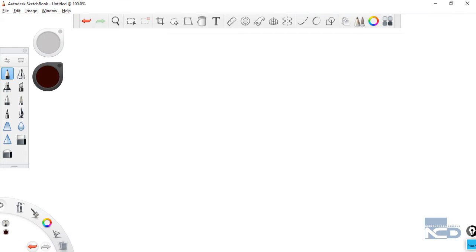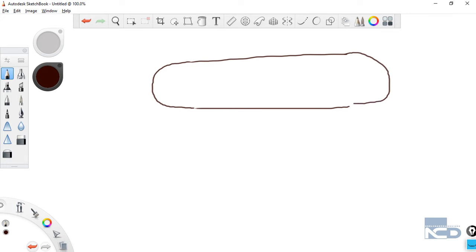For that I'm going to start my sketch. Basically a slot is made up of two kinds of objects, parallel lines and semicircles. There are two parallel lines and two semicircles inside a slot. So you have two lines that are running parallel, connected with the help of arcs, and this is how a slot looks. To dimension the slot, you just have to provide the length value between the endpoints of these two lines and the radius of this arc. If you have these two dimensions, then you can easily define a slot.